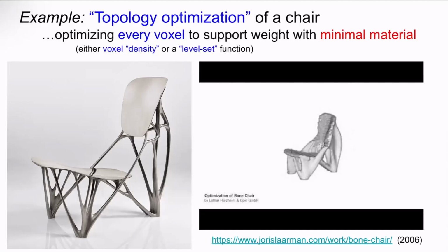But the shape of the chair is just completely free. So if you imagine you're going to start with just a block of metal, and you divide it into kind of 3D pixels, voxels. Every voxel you can either put metal or air. Okay, this is called topology optimization. Topology in math is like how things are connected. Like is it one big thing, or are there holes? How many holes are there, and so forth. And we're going to leave this completely free. So the computer is going to decide where to put the holes, or if there are holes, and so forth.